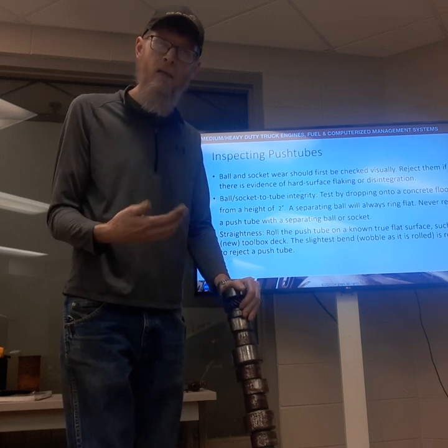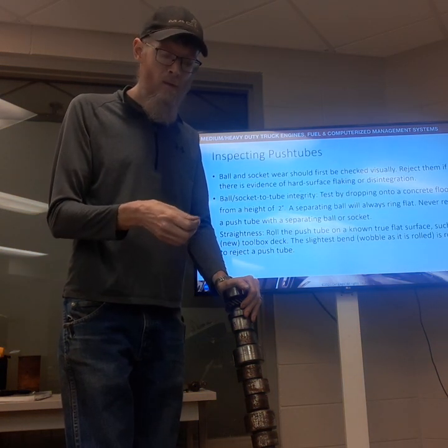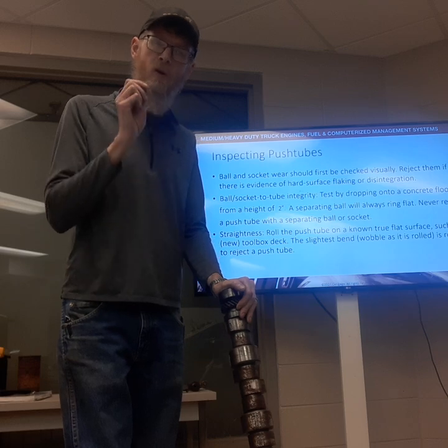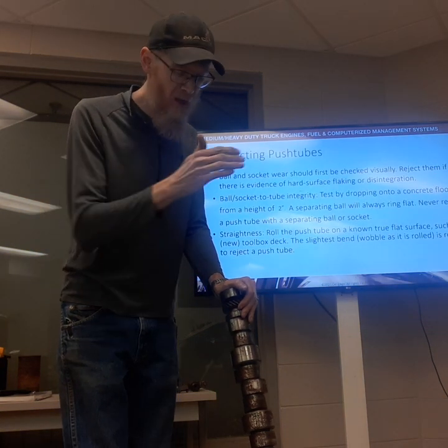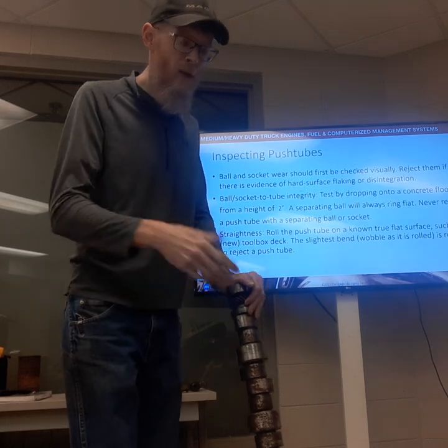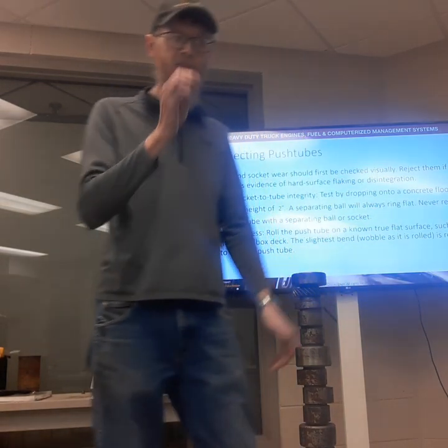Ultimately, if the wear is bad enough, the amount that our valves are opening is going to be affected. If we take surface material away from our cam lobe, ultimately, it's going to affect how much travel we get from that cam lobe.